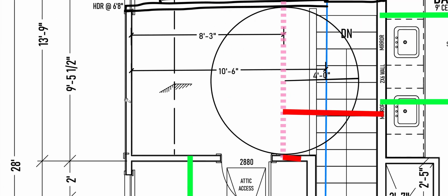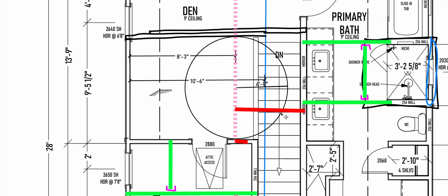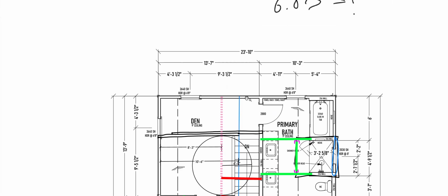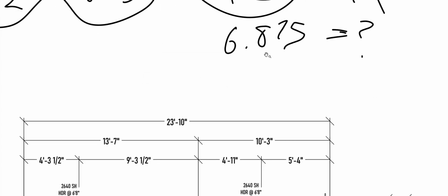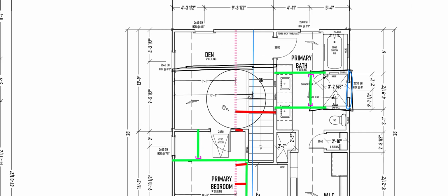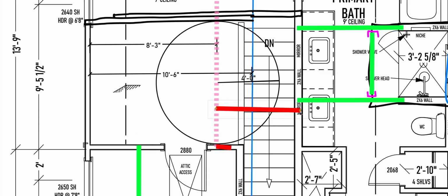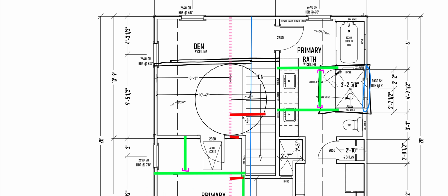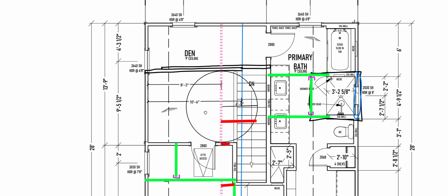Because we're bracing on the 9-foot wall, but that was a 7-foot wall. So we lost 2 feet because this wall's taller. Let's say I had 6 feet up. I lost 2 feet because of the wall height difference. So I only actually have 4 feet above the 9-foot wall. I can tell you without a doubt that I cannot reach this wall, because there's my 4-foot circle right there. So this brace isn't going to work. I can reach that far, because 4 feet with a 45-degree angle, but I can't go all this way.